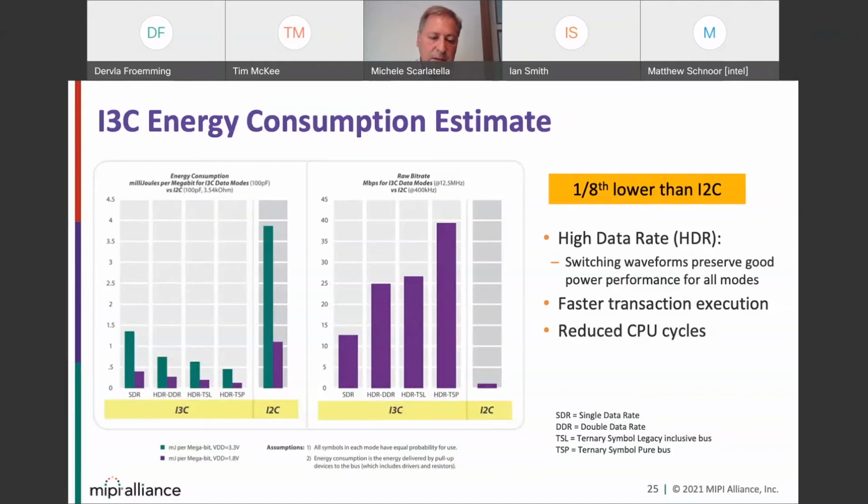The standard data rate is, let's say, I2C similar. There is a double data rate, and then there are two additional ones, the ternary. They use ternary signaling, and I just noticed that those two are not available under the I3C Basic specification. There is also a fourth data rate, called burst mode, which is really an improved DDR, just a continuous stream of bits with the CRC.